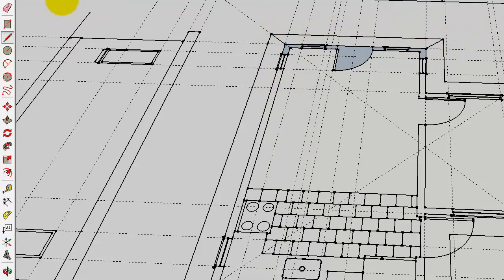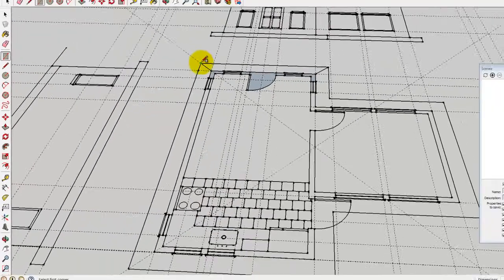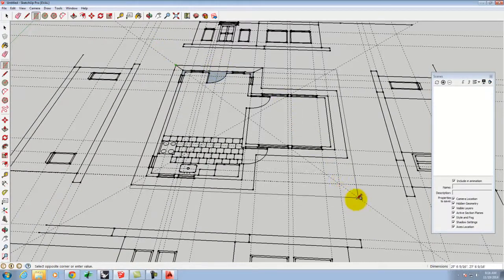It should. The other option is to go ahead and use your rectangle tool and to draw a big rectangle surface, right, over one of these surfaces. And you can see that it's starting to build out surfaces, and I can see them in this kind of bluish color. There's not a right way or a wrong way to do this. We're just trying to build some surfaces in. And SketchUp can be a little bit finicky when it comes to this.